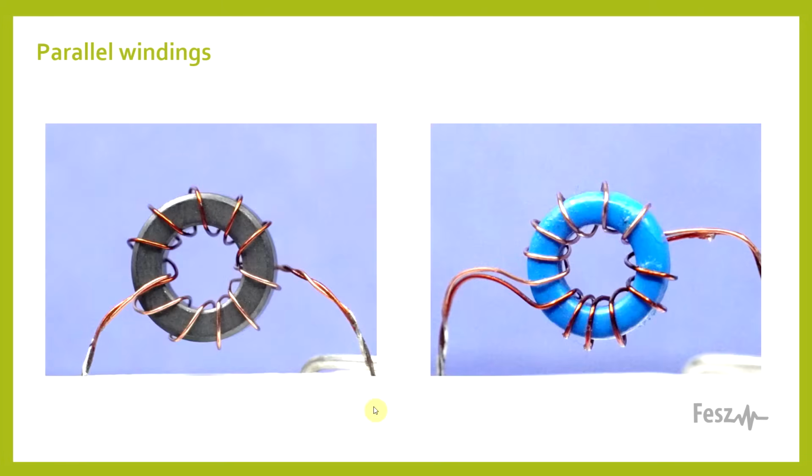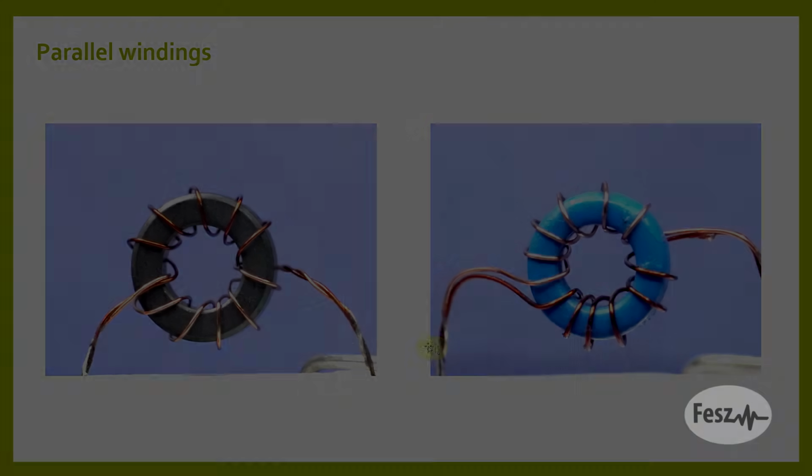The third method involves coiling 2 coils in parallel, both starting at one end and ending at the other. So while there are 12 turns in total, it's 6 in parallel with 6. But since they're on the same core, the end result still behaves like a single 6-turn coil. This should also reduce circumferential current, but you might have an adverse effect on capacitance since there is far more surface area. We'll just have to see how this works. Now, I'm not going to get any surprises, since I know exactly what the cores are.